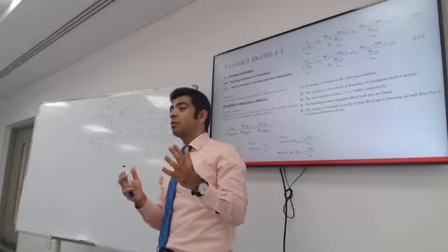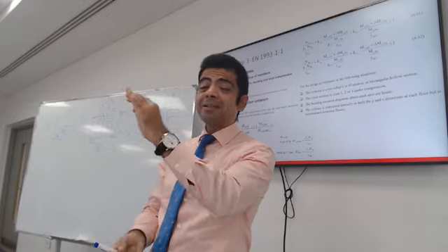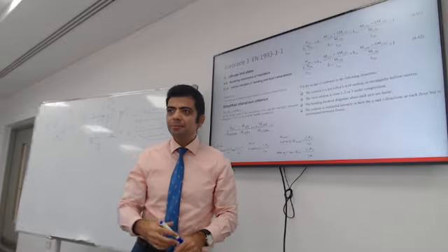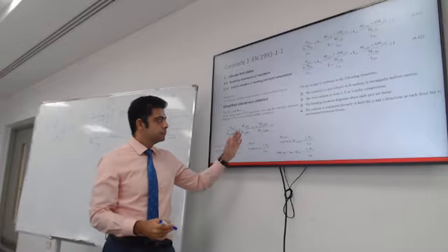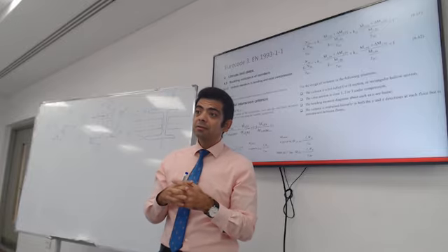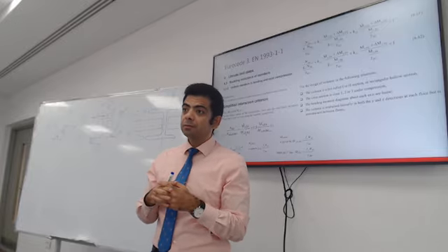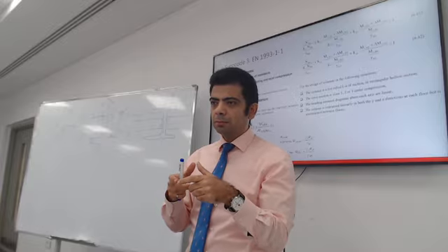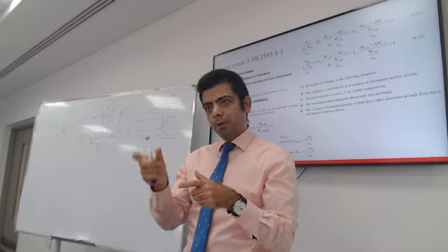So back to my question. Can someone summarize how to design a column under axial load and double moments? You add them all together and it must be less than 1. Yes. So what are you gonna add up together? Moments. Okay, the actual moments on the column? The moment directions I have are about z and about y.